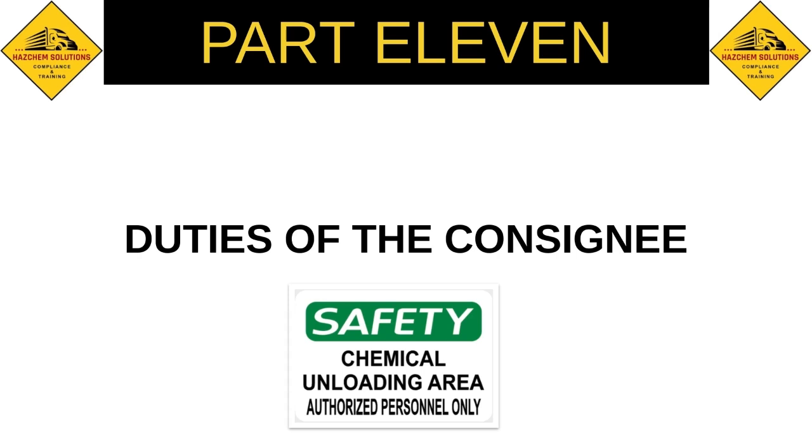Now, some of the duties for you as a driver is that you must make sure that the operator card is displayed on the vehicle and that the vehicle is roadworthy. And the vehicle must also be fit to use by going through the checklist at the start of the journey. That's for yourself. And then the vehicle must be free from any product likely to contaminate the load or create a danger. Now, before you load any dangerous goods, you must make sure that the site is suitable for the operation and that the vehicle is positioned and directed for loading. And make sure that you have been given permission for loading to commence by either the consignor or the qualified person.